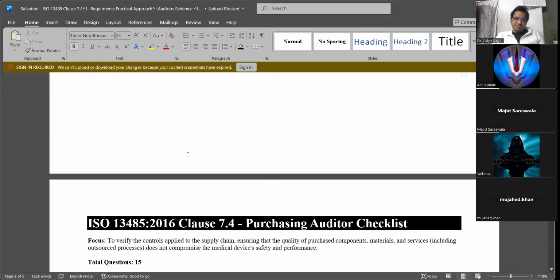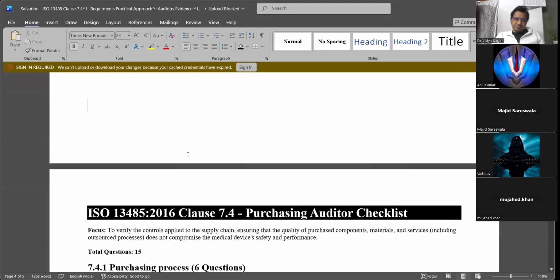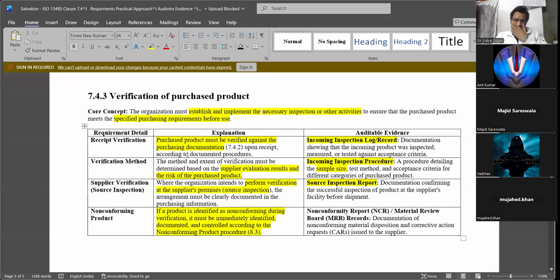There is a table in ISO. I am not able to recall the name of the ISO. So it has that if you have less than 100 batch size, you need to take 2 or 4 samples, whichever is more, and more than 500, then you need to take 2 or 10, or 4 or 10% of the total lot size. So based on that, we can calculate.